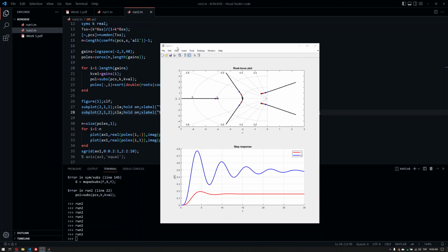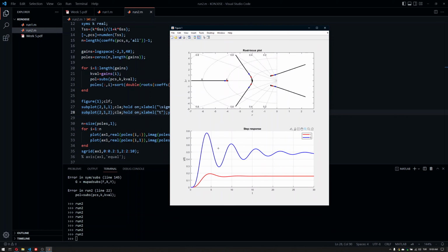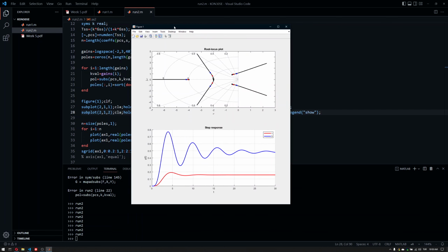Of course, this is just basic root locus and basic controller tuning. And the most basic controller is called the P-type controller, which is practically a gain only. We can show more visual data about this, but this is sufficient at this point. This is a basis for controller design.